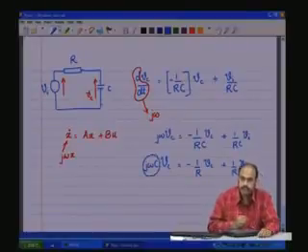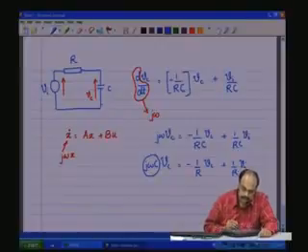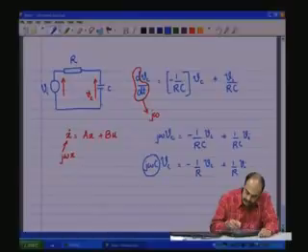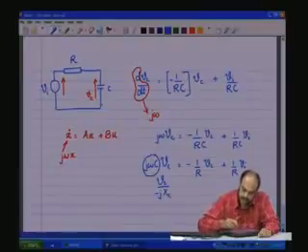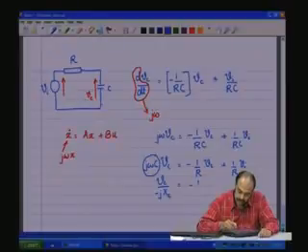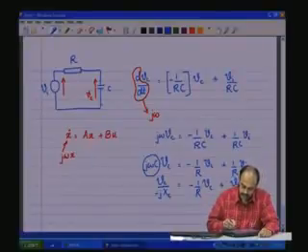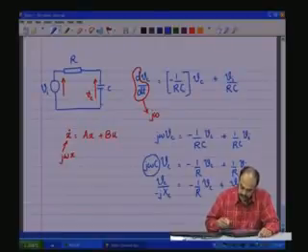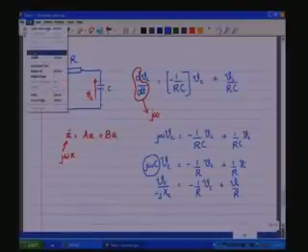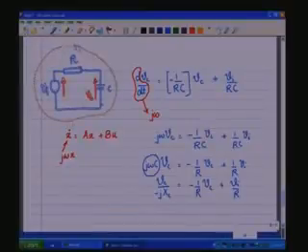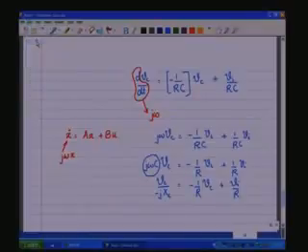this is nothing but the capacitive reactance part, which can be written as Vc by minus jXc, which is equal to minus 1 by R Vc plus Vi by R. So, when you rearrange it, that is, you take Vc on this side and then on rearranging you obtain, let us have this circuit with us, copy, let us paste it here.